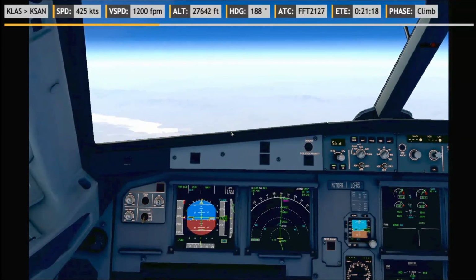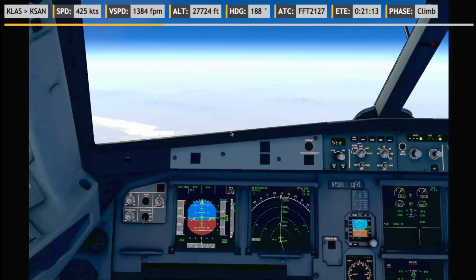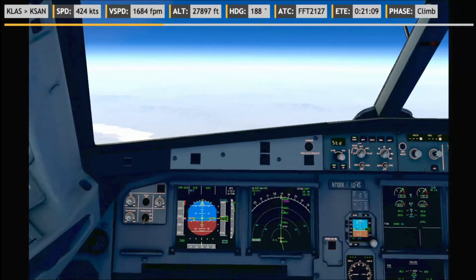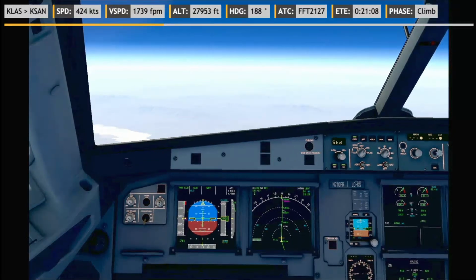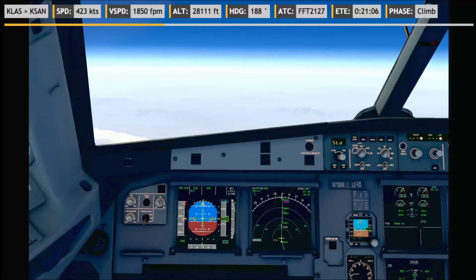Alright, I think this is a good time to start doing our descent brief. Our briefings. So we're gonna be flying from cruise level down the Lucky One arrival. First restriction is MOMAR between flight level 240 and flight level 260. Next, DESERT between 190 and 230. Then Trixie at 270 knots between 14,000 and 12,000 feet.